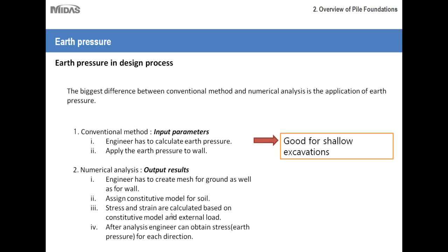And then next, you have the stress and strain that are calculated based on the constitutive model and the external load. Actually, when you're doing a numerical analysis, you don't have to calculate the earth pressures yourself. All you have to do is have the ability to create a model for the program to analyze. Once you do that, the program will calculate all the earth pressures for you. So instead of understanding how to calculate earth pressures, it really comes down to being able to model them accurately by creating the geometry and selecting the correct constitutive models.